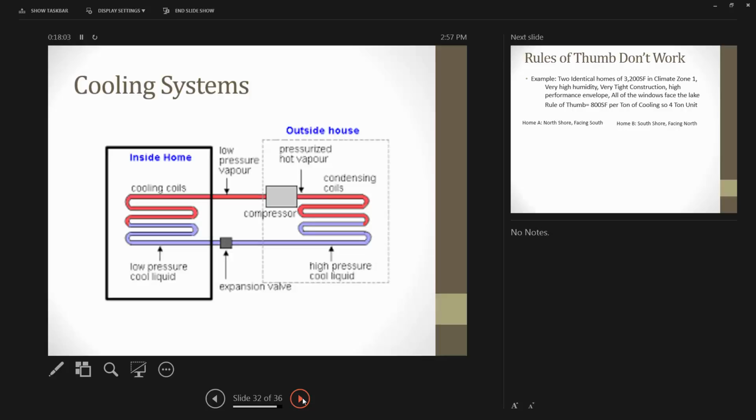What happens is blowing that warm air across the colder coils, and by doing that, not only is it cooling off that air, but it's taking the moisture in that air and causing it to condense. So it's also pulling that latent heat out of the air and reducing the humidity, and that's what makes the air conditioning unit work.